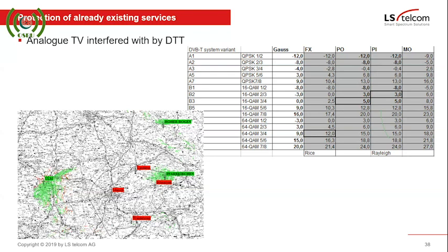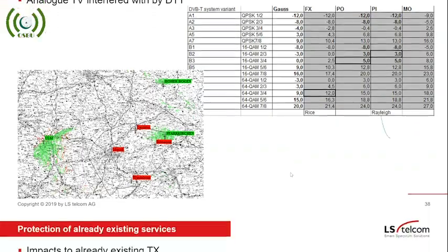You might introduce a different frequency than the final frequency for your DTT network. And once analog is switched off, you will, through a coordinated process with the viewers, inform them of the frequency change, so that it's as unintrusive as possible to them, and will not cause unnecessary loss of signal where they're not informed about the change in frequency.